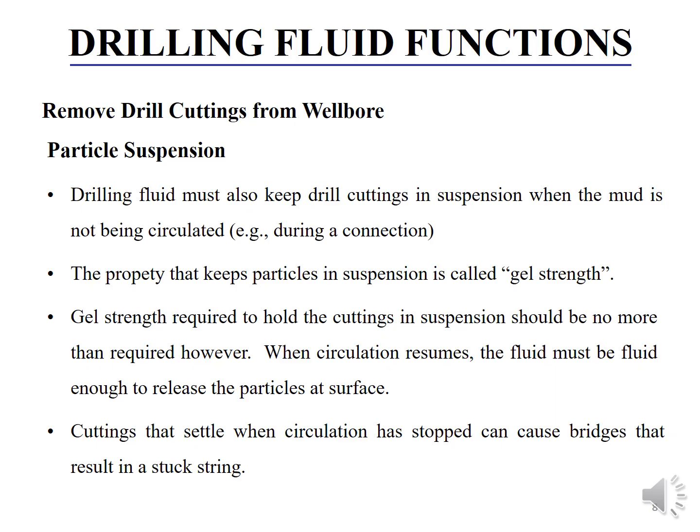Then particle suspension. Drilling fluid must also keep drill cuttings in suspension when the mud is not being circulated. The property that keeps particles in suspension is called gel strength. So gel strength of the mud is the first and foremost basic property. Then the gel strength required to hold the cuttings in suspension should be no more than required. However, when circulation resumes, the fluid must be fluid enough to release the particles at the surface. Cuttings that settle when circulation has stopped can cause bridges that result in stuck string.